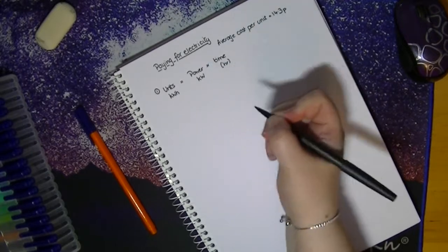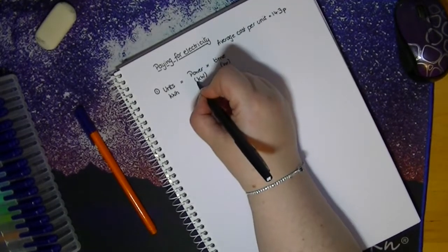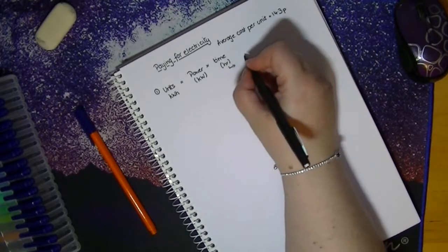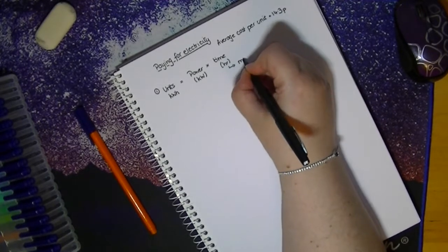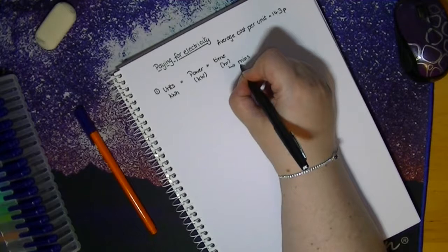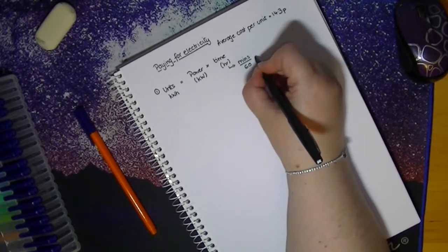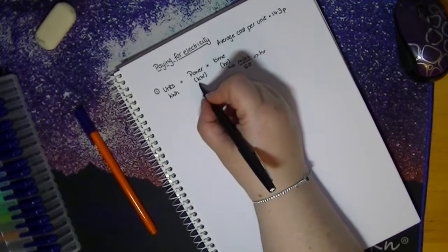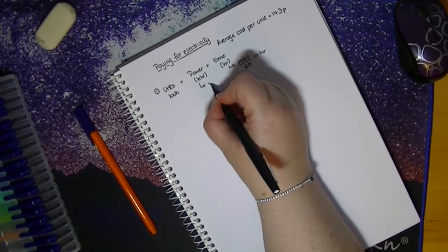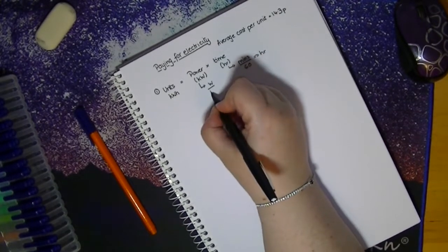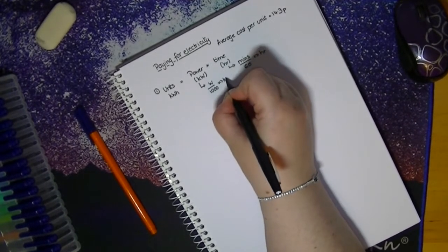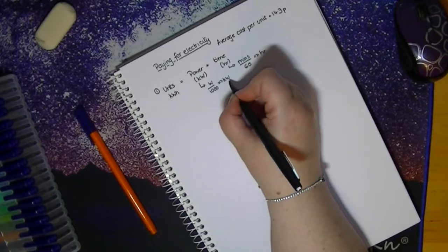So that means if I'm given either of these in a different unit, I've got to transfer them across. Frequently, I'm given time in minutes. If that's the case, I do the minutes divided by 60, and that will give me the time in hours. I'm often then given the power in watts, and if I've got that, I divide by 1,000 to give me kilowatts. Exactly like meters and kilometers.